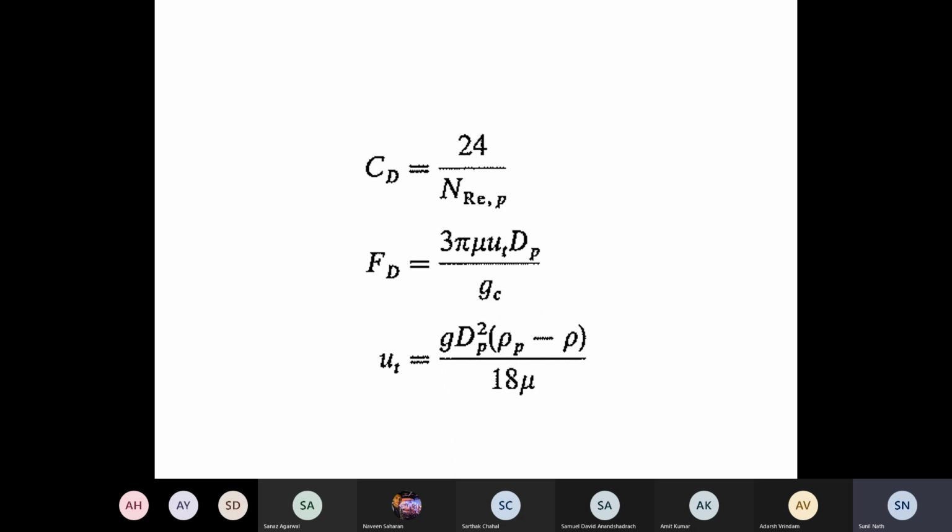And if somebody has done this, I would challenge them to go to the high Reynolds number region beyond 2100 RE, and that is called the Newtonian regime, just as this was the Stokesian regime below RE less than 1 until 10 to the power minus 5. So something like 2000 to 10 to the power 5, or 2 into 10 to the power 5, we'll call Newton's regime.